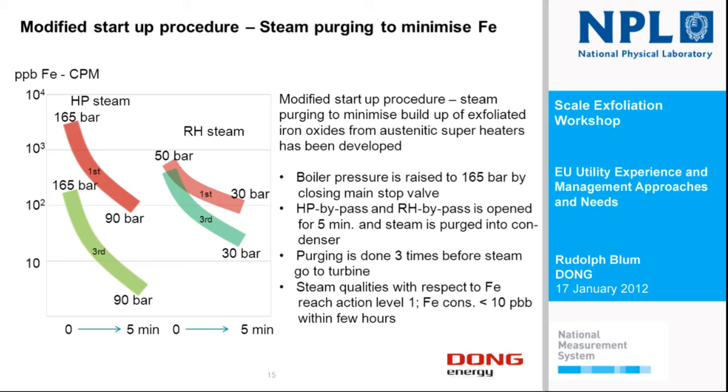And you see also what happened. This iron measurement has been made very carefully, because making iron measurements in steam is difficult. You need a real isokinetic sampling, and that we have. That means you need to take out a large amount of steam and cool it down in a cooler, which is constructed in such a way that you have proper cooling.